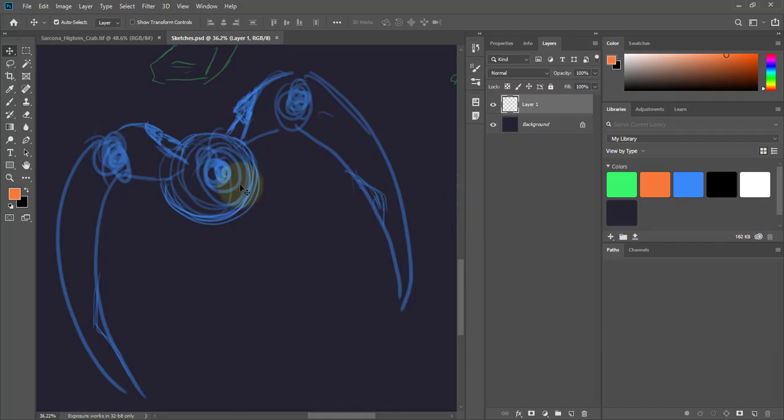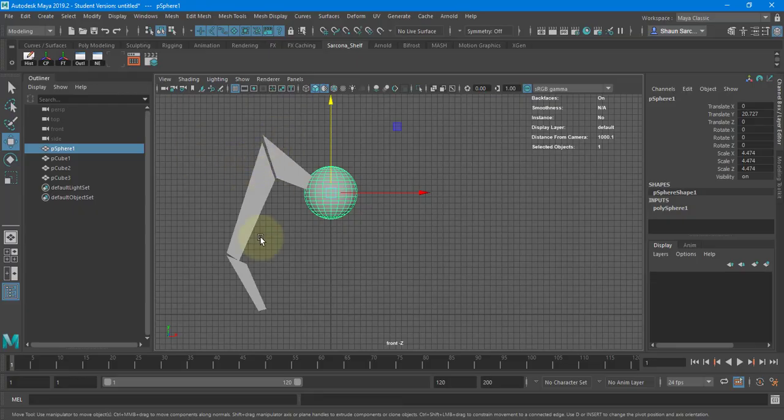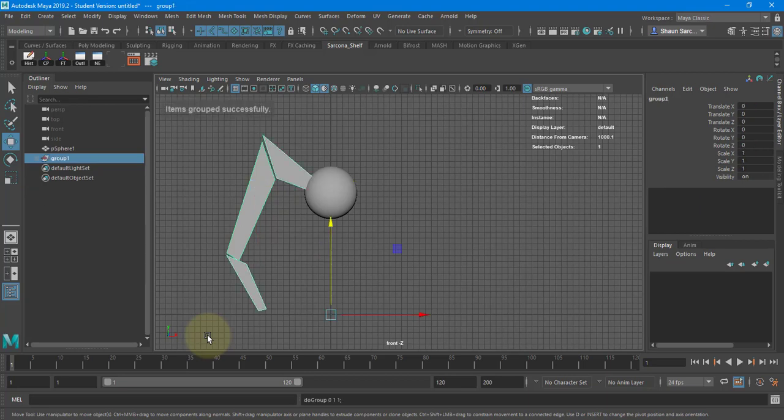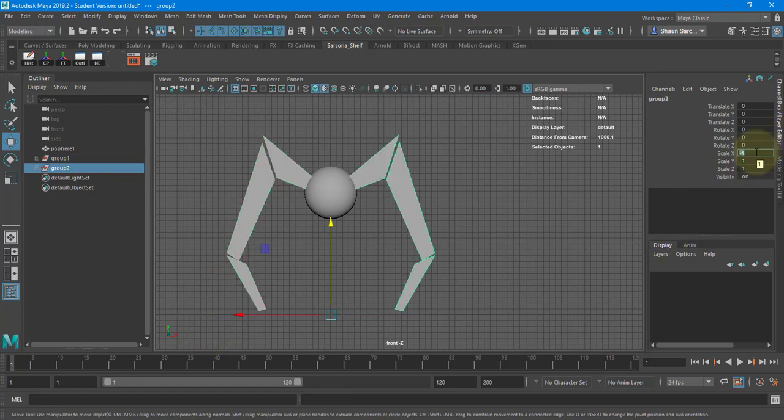I also don't move stuff away from the center. That's main. So this is my item. That stays right in the middle of my grid. That is the center of my world as far as I'm concerned. And the reason for that, I need these things to be on the other side. Watch how I can group. Control G. If you watched the hotkey video, you'd know that. Control D, another hotkey. And then I'll go to the scale X and make this a -1.